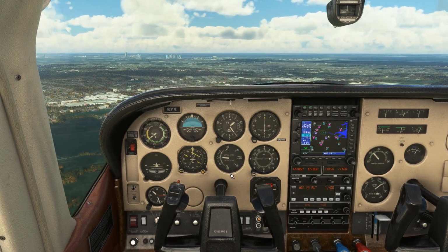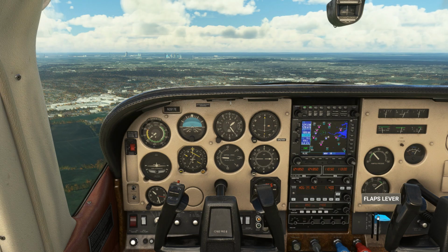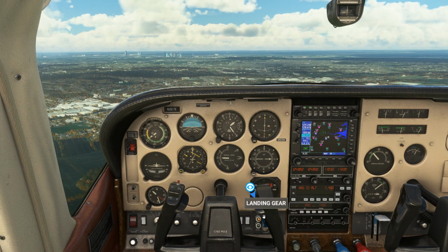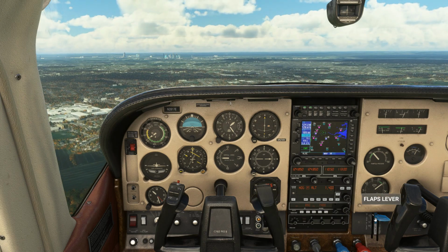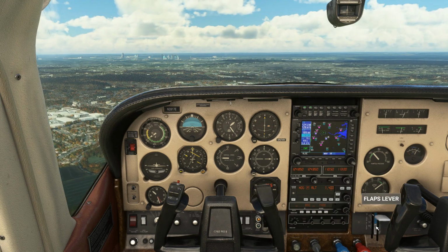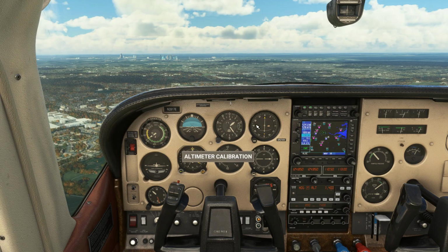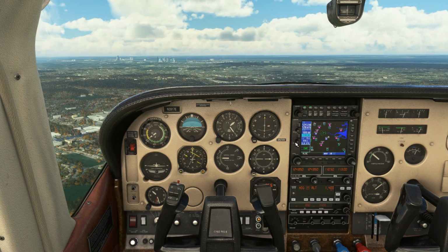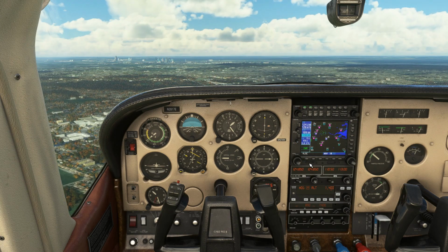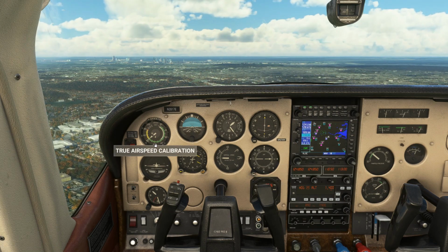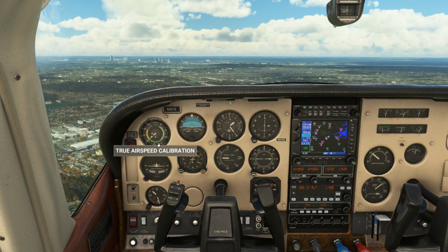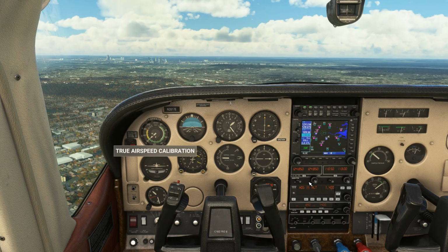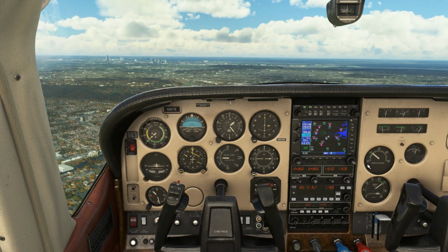So I'm just going to keep an eye on this, and I'll be physically using my physical landing gear to bring it down, and physical flaps here in the aircraft to bring them down, keeping an eye on my airspeed. I'm going to bring my throttle back to 50% now. There we go, because I want to get it around here, this marker for gear down speed, and then try to get it into flap speed gradually.